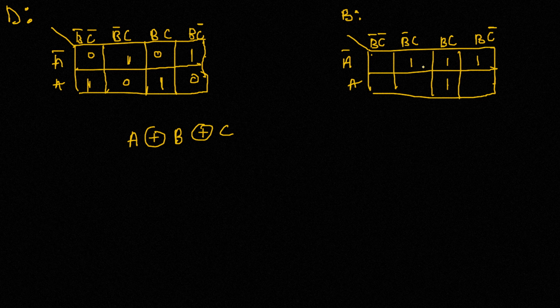Okay, so again, like I mentioned for half adder, for full adder, the normal way of grouping K-maps is not going to help us get an actual simple logic gate diagram. So what we do is we group these two ones alone, and these two ones are taken as it is. So we have A complement B plus A complement B complement C, which is this one, and then ABC.